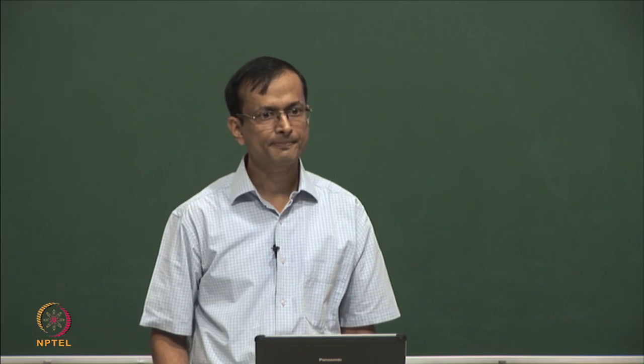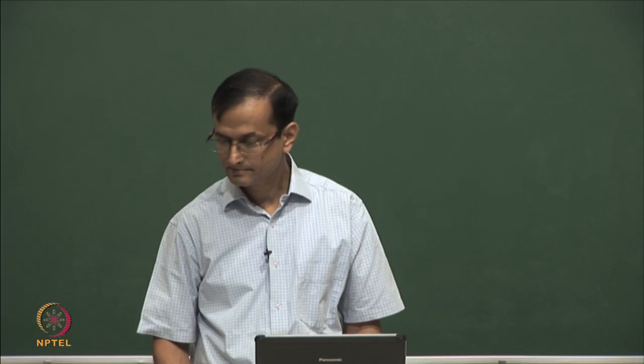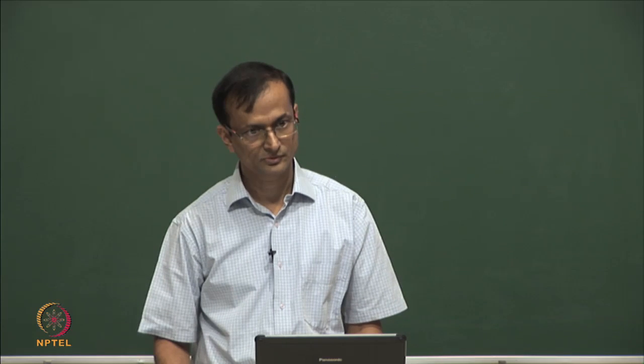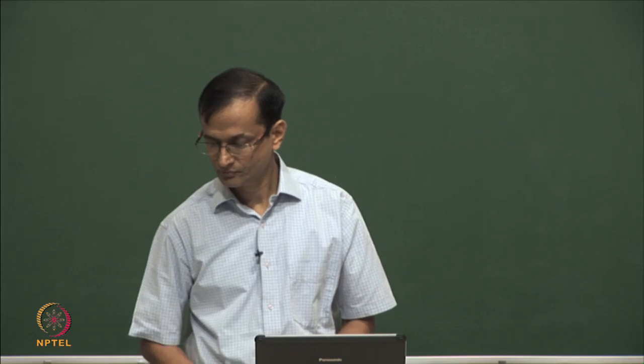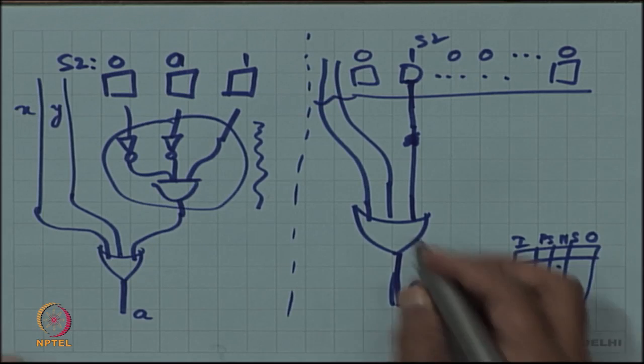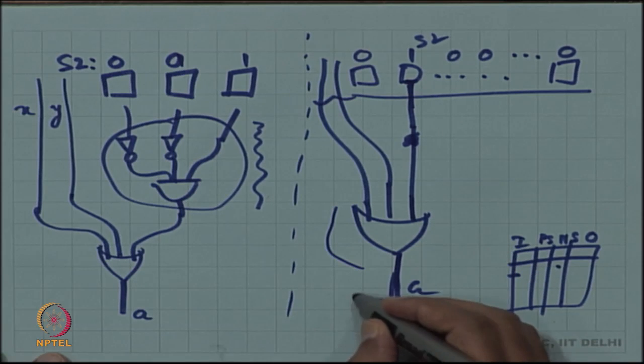Sir, why do we need all 7 lines going forward? Because if we know that we are in state 2 and the next state is going to be state 3, we need only 2 lines. The state 2 should be set to 0 and 3 should be set to 1. All others are already 0 when in state 2. This is the implementation of one transition.